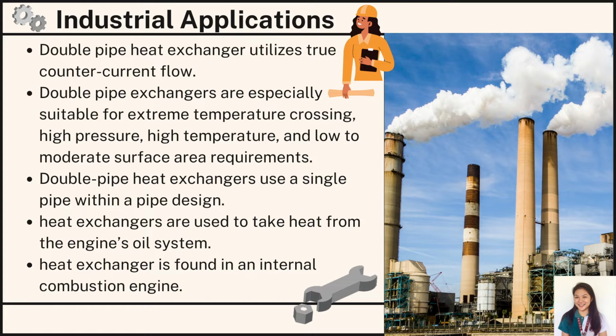In commercial aircraft, heat exchangers are used to take the heat from the engine's oil system to heat cold fuel. This improves fuel efficiency as well as reduces the possibility of water entrapped in the fuel freezing in components.